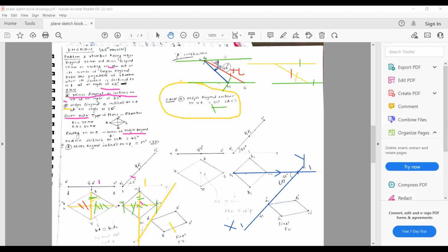Okay, and repeat the procedure as usual, taking the projection from A, go with A perpendicular to the x1 y1 line, go with B, I think it will be coming on the same, take the projection through C, take the projection from D, and take the measurement of the concerned point A dash. A dash is on the XY line itself, so the A dash point will be here.